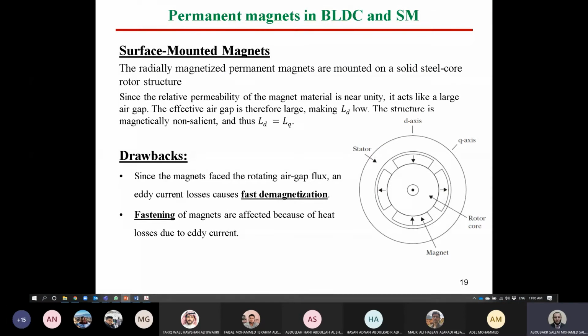You know, Shabab, the excitation in a synchronous machine is very important in order to establish the flux. We have two ways: either using windings, like brush or brushless excitation, or using permanent magnets. Permanent magnet is also a good solution. However, take care, permanent magnets are not preferred in hot areas, here in the GCC.